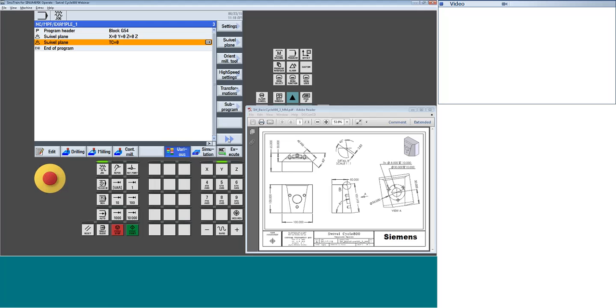Make sure everything's square and straight. Shut off my tool carrier. Now, in this case, I don't necessarily need to shut off the tool carrier because I'm going to be using it the whole time. But the first thing I need to do, once I know everything's clear and it's happy and it's a safe spot, is I need to machine, to look at your print, right there in this middle view, this first projected view, I need to machine a 9-degree plane. I got to machine off this face 9 degrees. So I'm going to do that with the facing cycle, but I'm first going to get my tool in orientation using the swivel cycle. So go to swivel, turn it on.